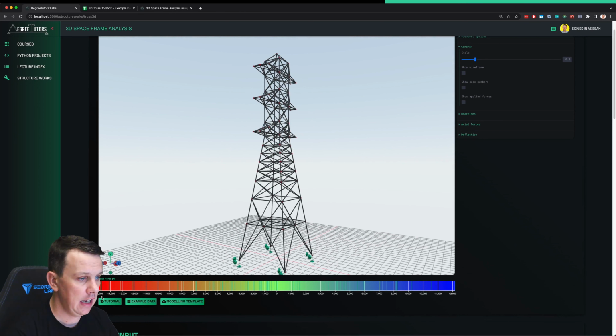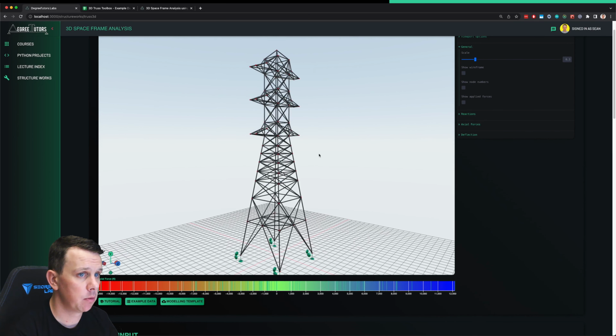So you've got a color scale essentially, which will correspond to the colors of these elements when I go and view the axial forces. And if you're wondering what all the little green vertical lines are, those just indicate that you have one member with this particular axial force. Is it useful? I don't know if it's that useful, but it kind of gives you an idea of the distribution of axial forces within the members in your structure. You can see how they're distributed across the scale. Obviously the ends of the scale are set by the maximum tension and compression forces.